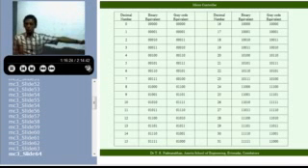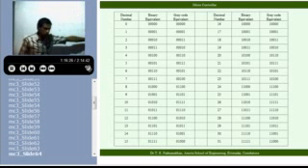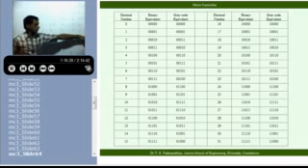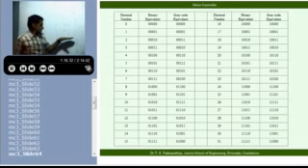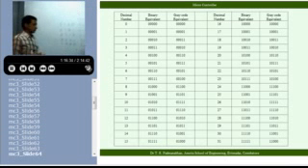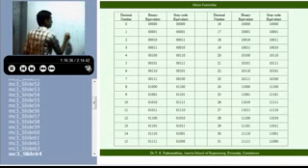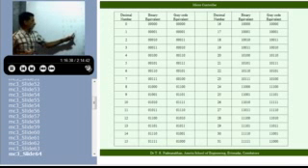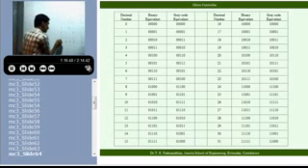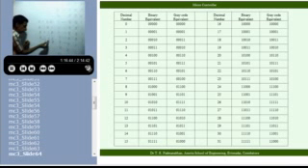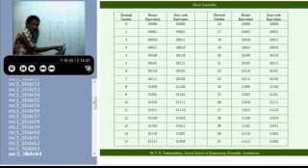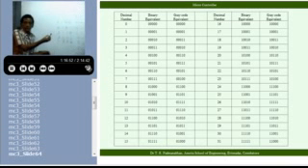If I use a gray code, if I just go on doing this, at any time when I change from here to here, there will be only 1 bit changing. In this area, only 1 bit is changing. First this bit may change, then this may change, then this may change. Depending on when you are sensing, there is a possibility it may be interpreted as 8 or as any of the other numbers.